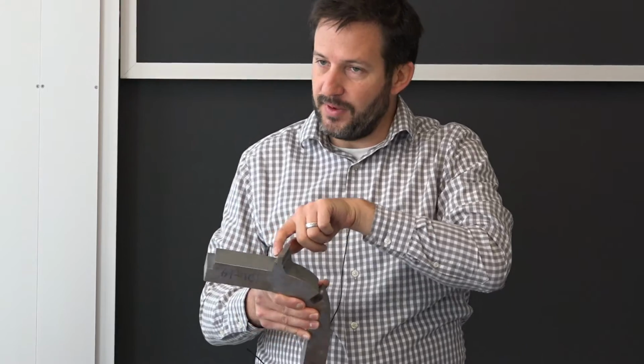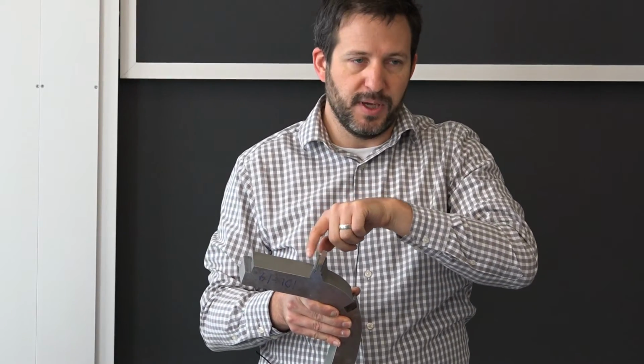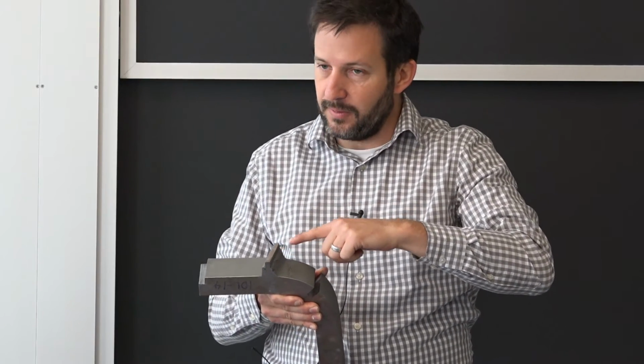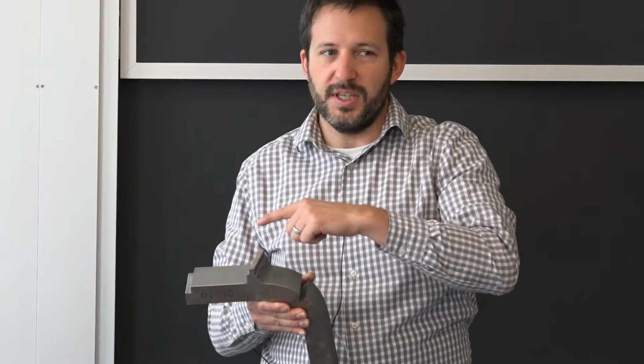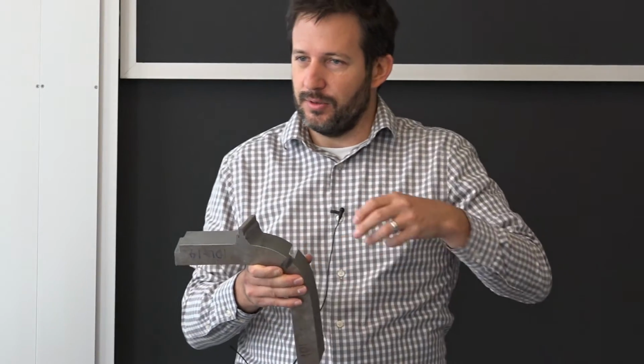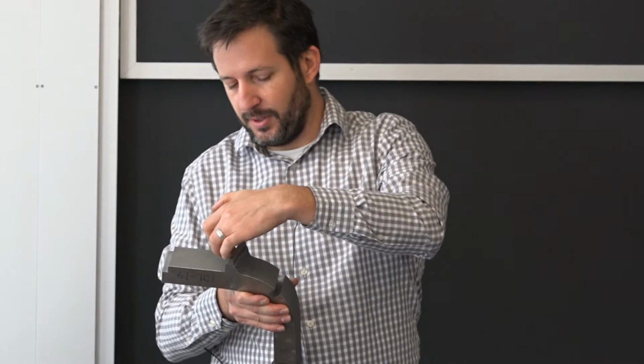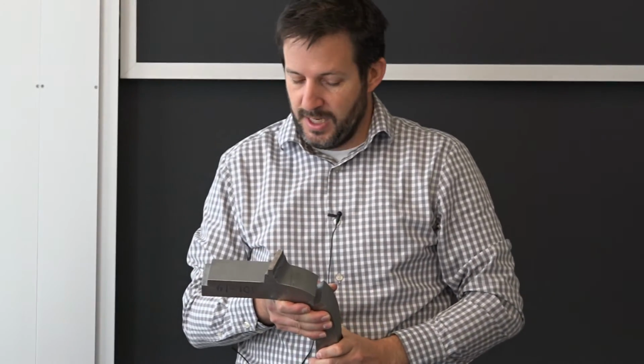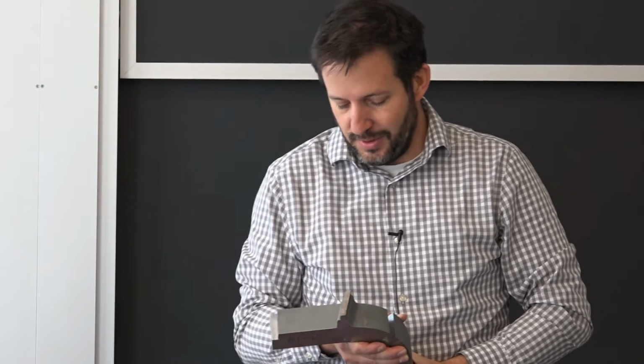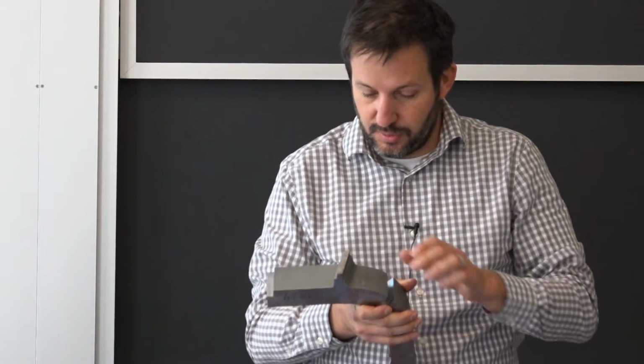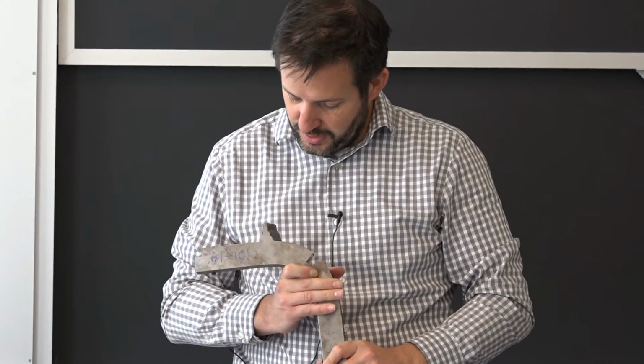By having a little bit of extra piece of metal behind, you're able to make that first weld a little deeper, and it's stabilized, it's protected. Because you can come with all your shielding from this side, but you'll have contamination there. So the code will give you an extra allowance for the stress level on that connection when you use those bars, and it makes sense because it is giving you better strength.